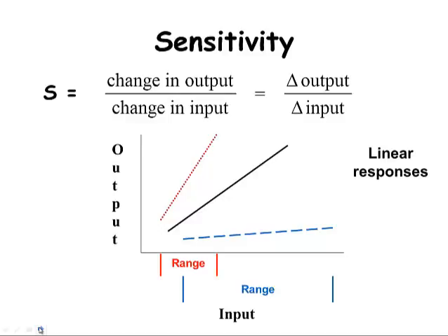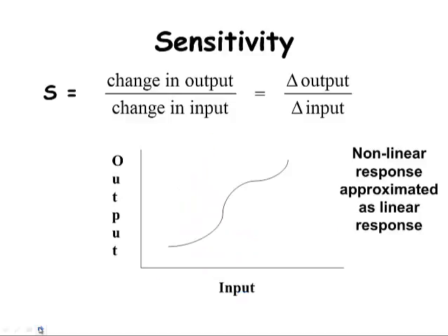The three lines shown here show a linear response between input and output. Most sensors do not have linear responses. Many sensors have nonlinear responses. Thermocouples, for example, which are commonly used to measure temperatures, commonly use ninth-order polynomials to describe the relationship between the input temperature and the output electromotive force voltage.